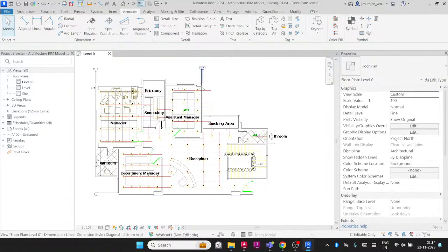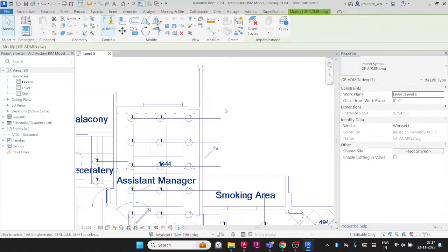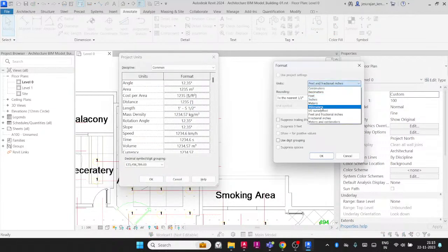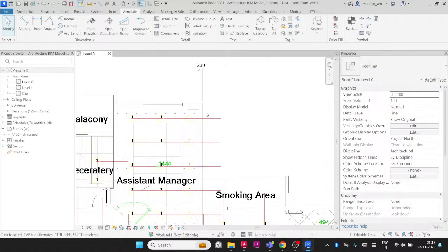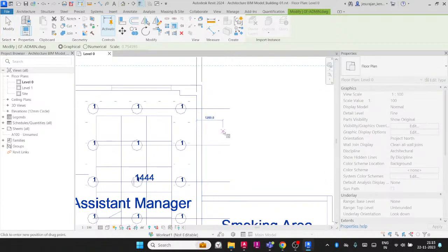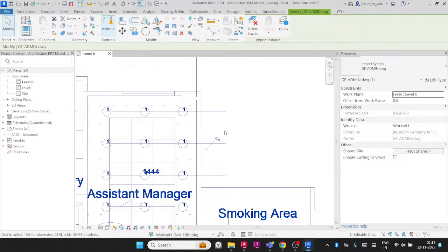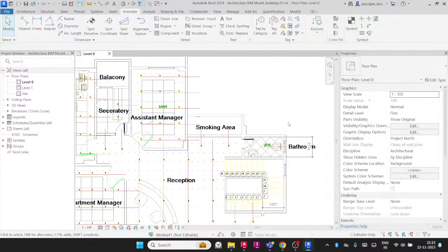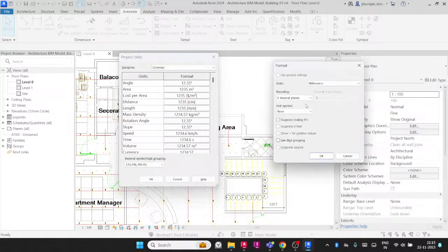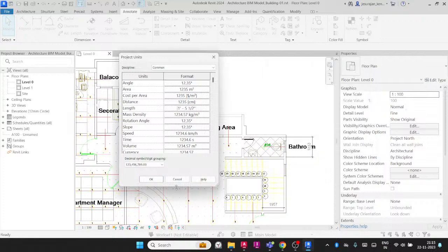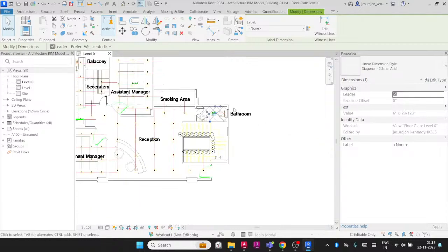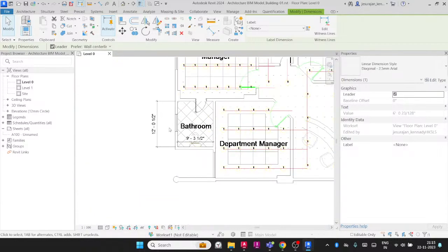If I measure here, it is 7 feet. Still it is more. So let us try to change this wall to 200. If I go to unit, you can toggle between the units, no problem. Okay, select scale, select the first point, second point, and type 200. Now they are 200. If I change the unit back to feet and fractional inches, now you see this is just 6 feet, but if we are getting a round figure, I think that's good.